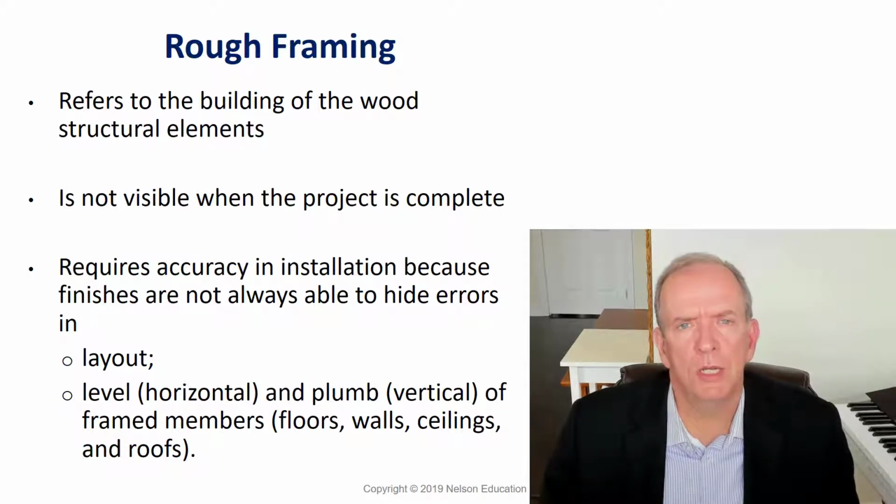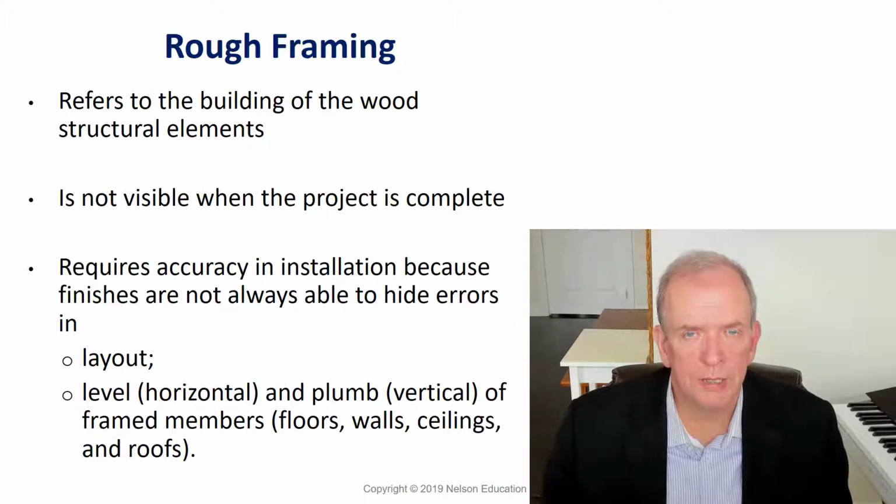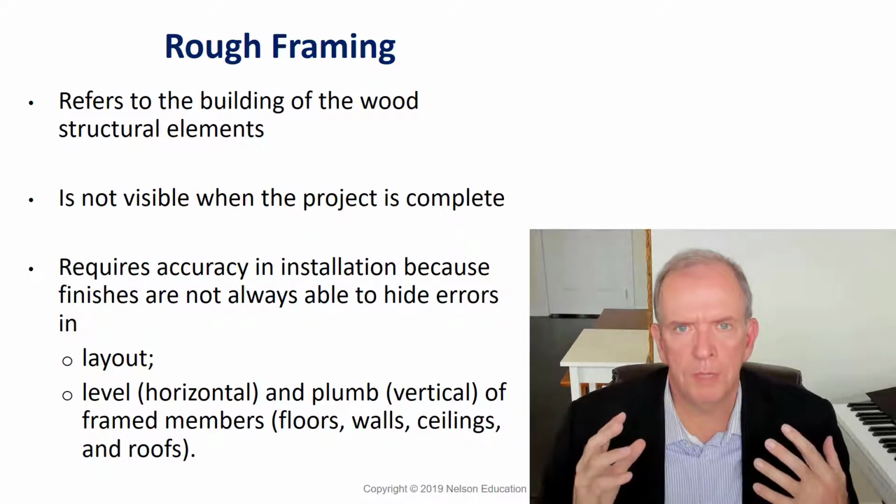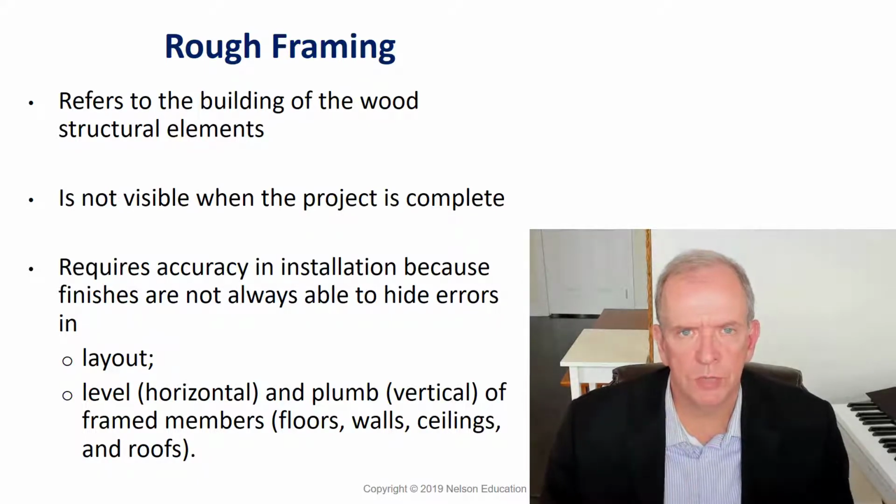One thing I didn't mention in the last lecture, I think that's worth talking about because we're talking about structural elements, is that stick framing, wood frame construction, is a very resilient method of framing. It's very resilient to earthquakes, whereas post and beam construction, timber frame construction, is more prone to problems.